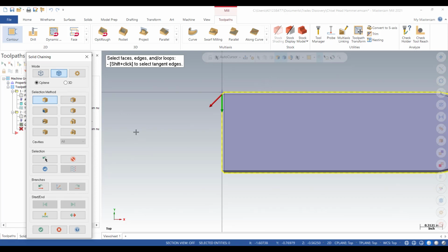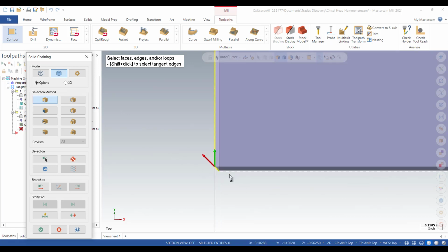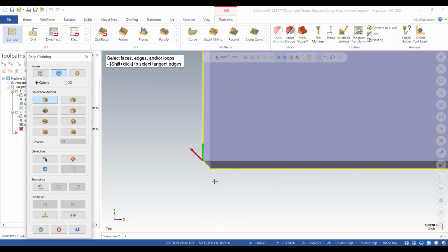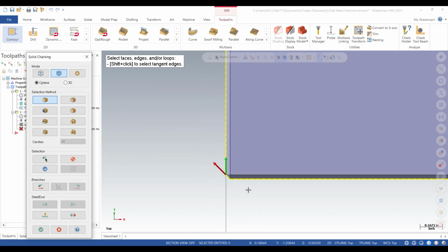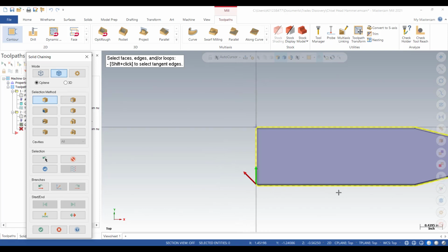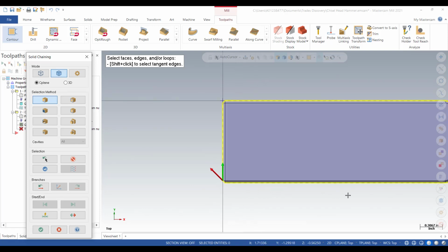So again, I'll just deselect that, unselect it, and then do it again. So the trick is we're going to click closer to this end so that the arrow goes upward, right? So that's how you're going to check it. Once done, the other thing, make sure we are picking the outermost geometry and contours. You don't want to, by mistake, pick the chamfer geometry. Once done, we'll say OK here.